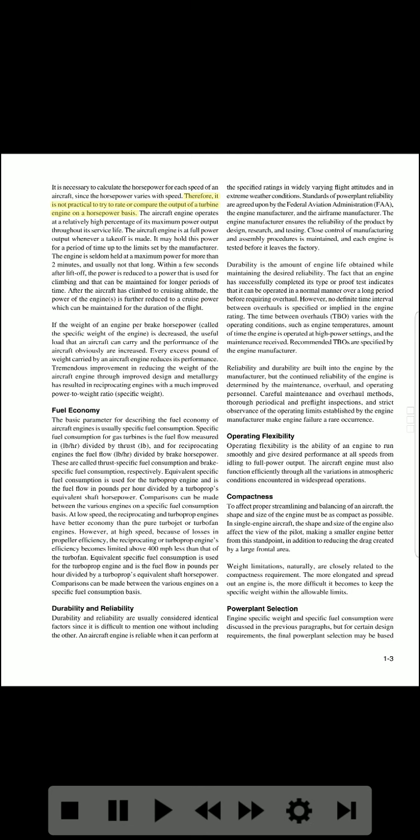The aircraft engine operates at a relatively high percentage of its maximum power output throughout its service life. The aircraft engine is at full power output whenever a takeoff is made. It may hold this power for a period of time up to the limits set by the manufacturer. The engine is seldom held at a maximum power for more than 2 minutes, and usually not that long. Within a few seconds after liftoff, the power is reduced to a power that is used for climbing, and that can be maintained for longer periods of time. After the aircraft has climbed to cruising altitude, the power of the engines is further reduced to a cruise power which can be maintained for the duration of the flight.